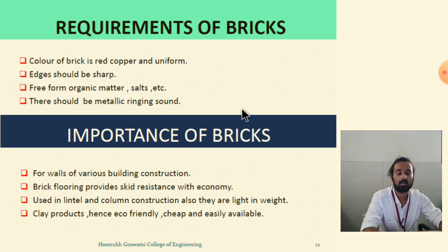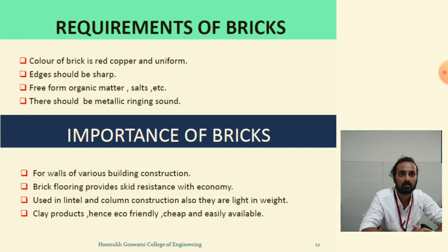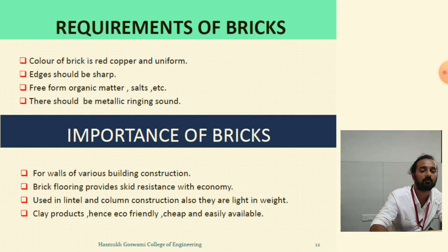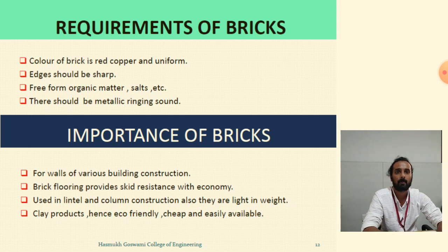Requirements of bricks: the color of the brick should be red and copper and uniform. Edges should be very sharp, free from organic matter. There should be a metallic ringing sound. Importance of bricks: you have been seeing that we use bricks in every type of construction, in building construction, flooring, lintels, column construction, clay products. They are very eco-friendly, cheap and easily available.